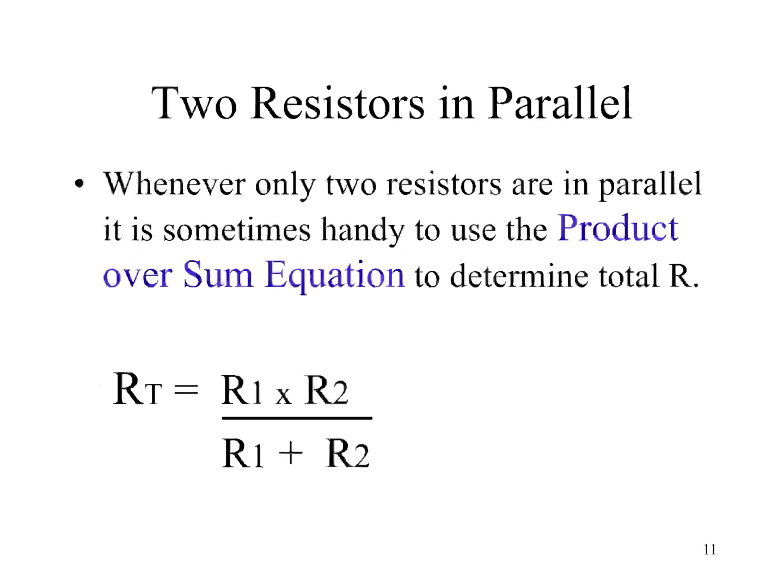So when it comes to working with parallel resistance, there's some shortcuts we can use a lot of times based on some of the rules that are around parallel connections. And one of them that's easily used and often used in circuit analysis is something called product over sum, and it's for two resistors in parallel.